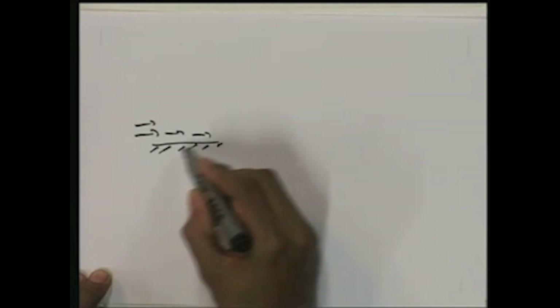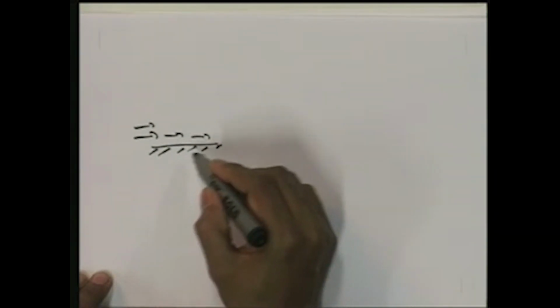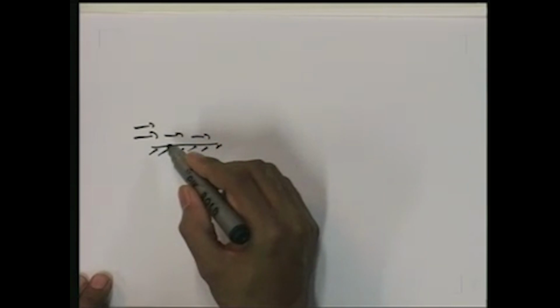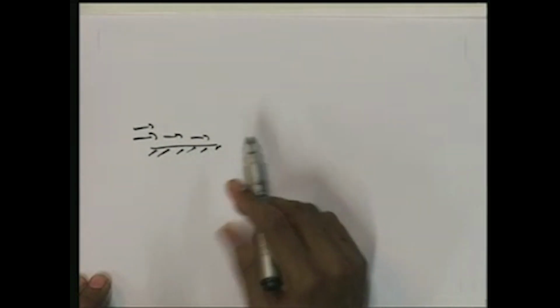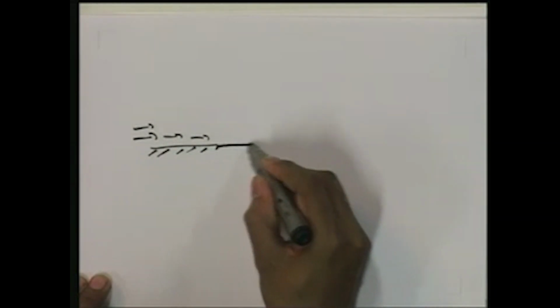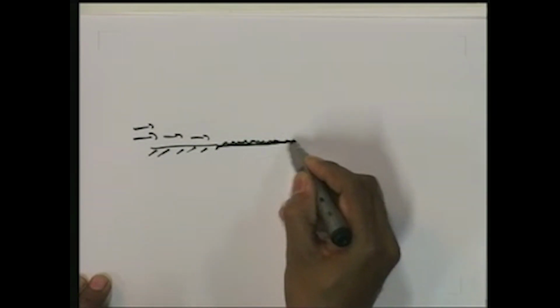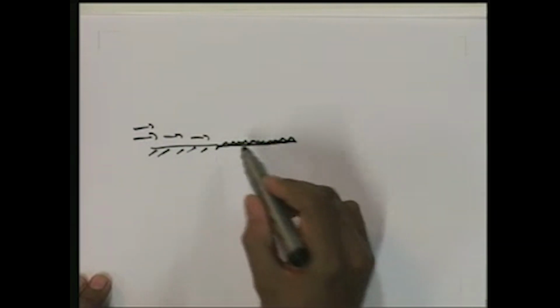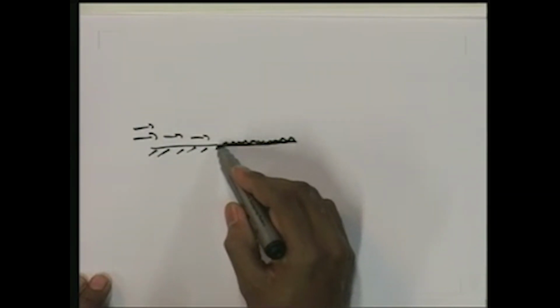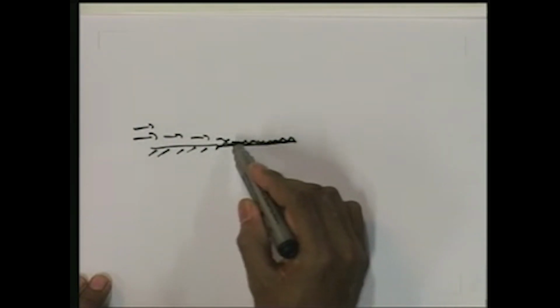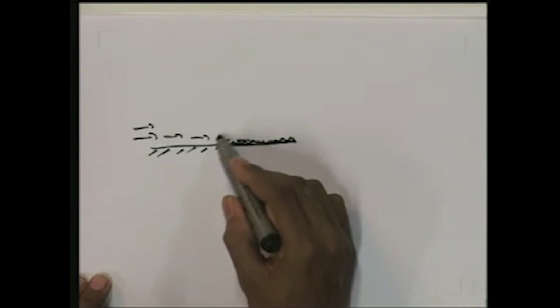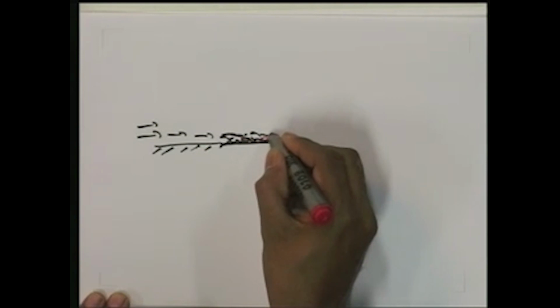Here the bottom wall is smooth, and if it changes, a small change here, that means the surface becomes rough, then due to the shearing effect the shear stress increases, and a small mixing starts here, and this laminar flow can become turbulent due to this reason.